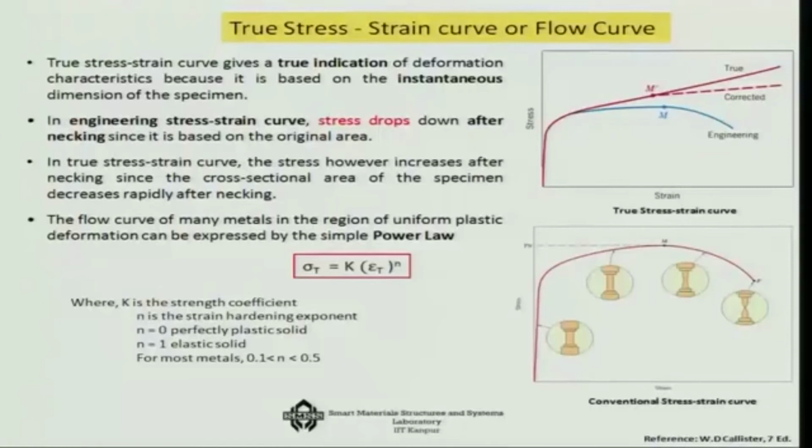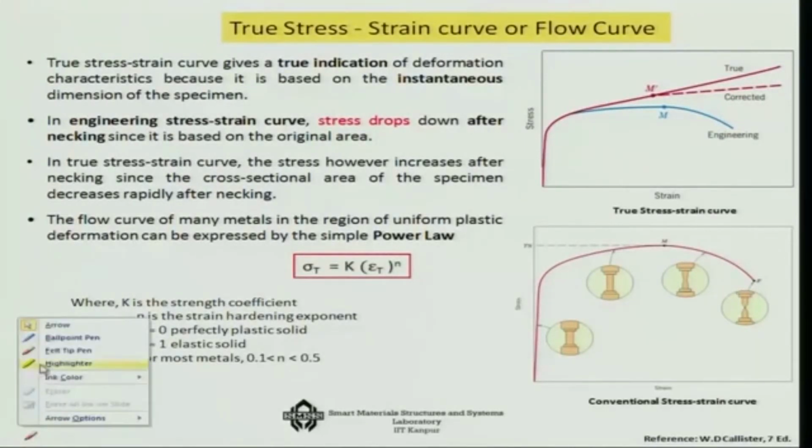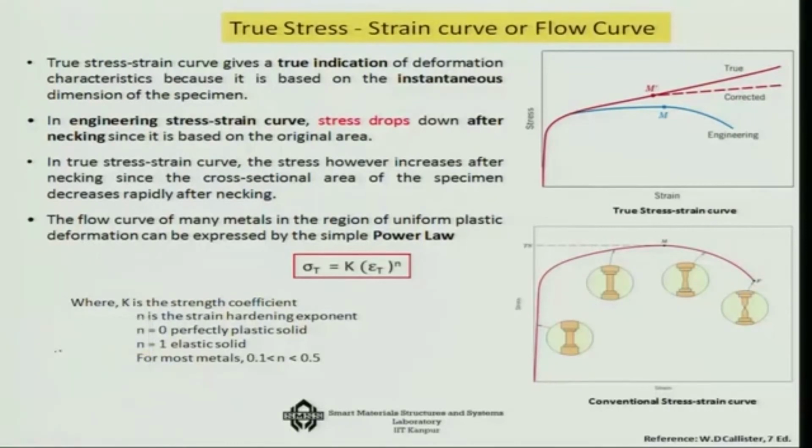if we consider, however, the true stress strain curve, that means if we consider that the area is actually changing, as you are deforming, this area is becoming smaller and smaller, the neck formation is happening.